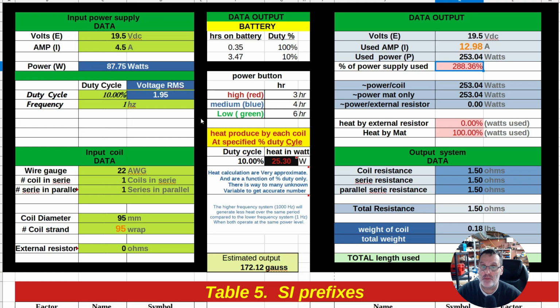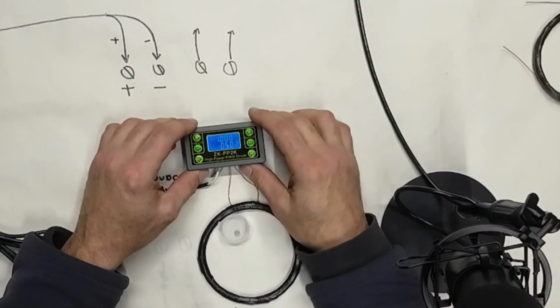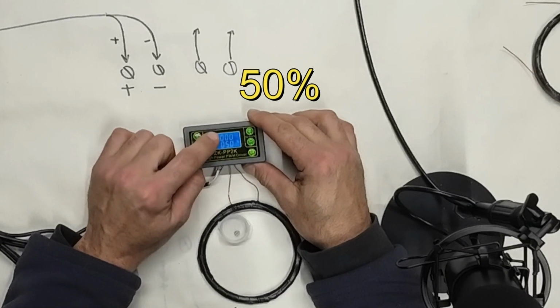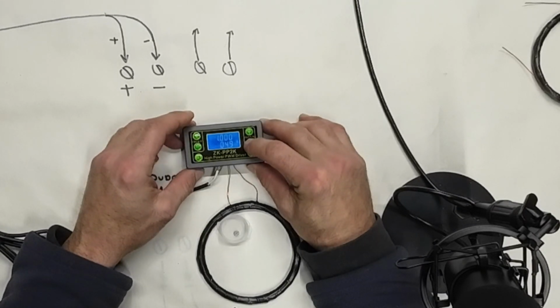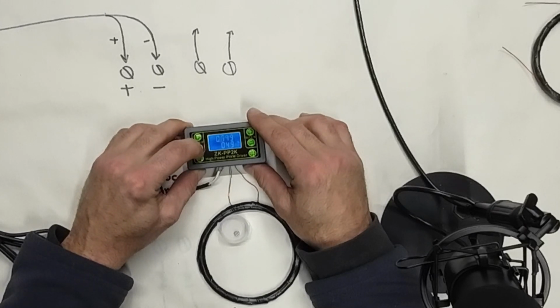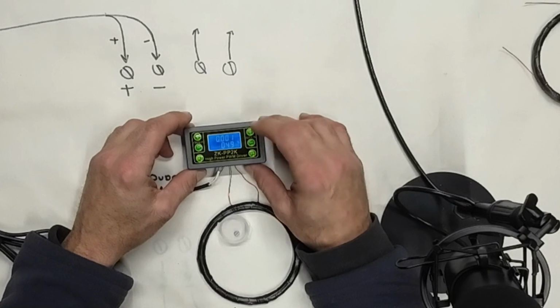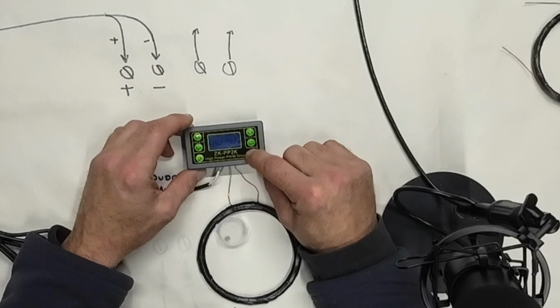I'm going to show you what would happen. You'll see the ZK will be pulsing. By the way, when you get your ZK right out of the box, it'll be at 50% duty cycle and 1000 hertz. The 1.000 is 1000, right? So bring that frequency back down to 1. Some ZK go to 0. Leave the duty cycle at 50, and then I got the on-off right here.